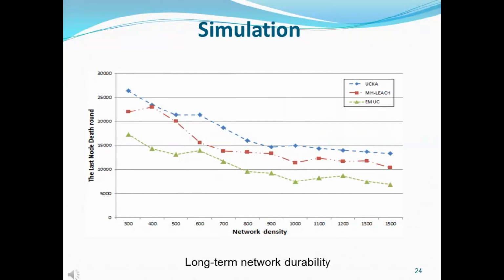Indeed, rather than using the conventional battery state of charge or residual energy during the clustering, our approach considers the battery degradation before the election of the potential cluster head. Moreover, the proposed approach assumes an unequal clustering scheme which alleviates the hotspot energy problem and further balances the energy consumption. Therefore, the approach exhibits better lifetime performance compared to the classical approach.